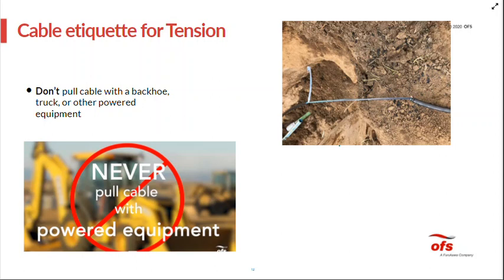But it's more than just that. You can exceed the rated cable load without breaking the cable. And when you do so, you can damage or reduce the long-term reliability of the fiber. So just because you may have gotten away with overtensioning the cable doesn't mean that you haven't damaged the cable. So again, please never use this powered equipment when you're installing the fiber cable.